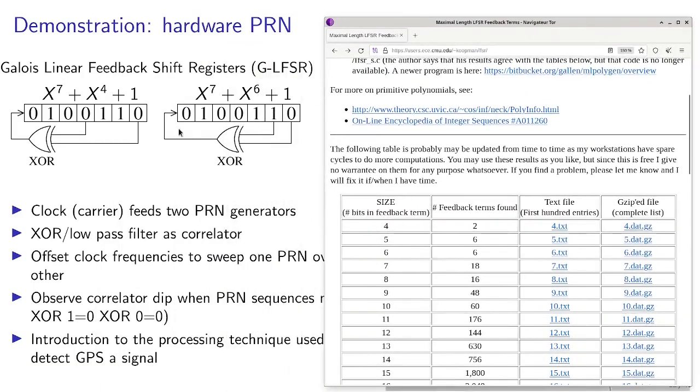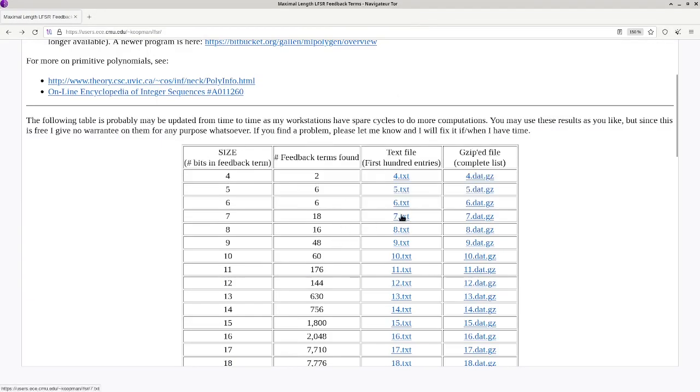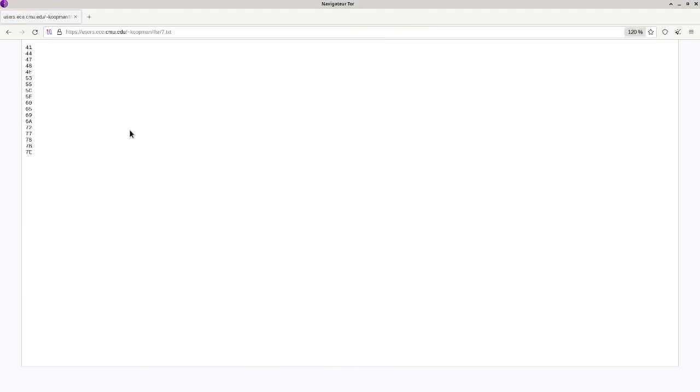If we look over here, we have selected a 7-bit long linear feedback shift register, so that we see in the entry over here that quite a few tap locations will lead to maximum length sequences. Maximum length meaning that the pattern cannot repeat, as 2 to the n minus 1 will go through all possible variations of the content of this register. Let us remember, for example, that register tap locations 41, this is hexadecimal, 48, or 60 are possible maximum length tap locations.